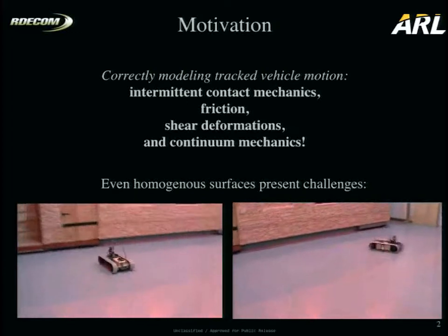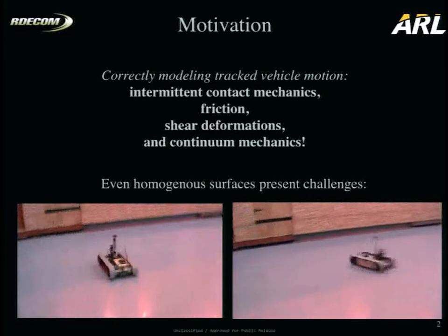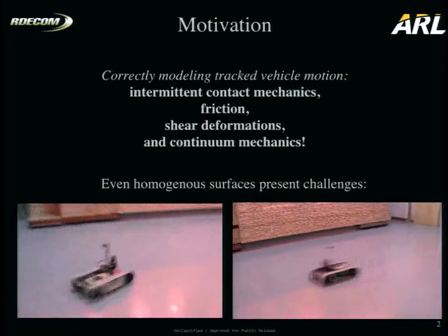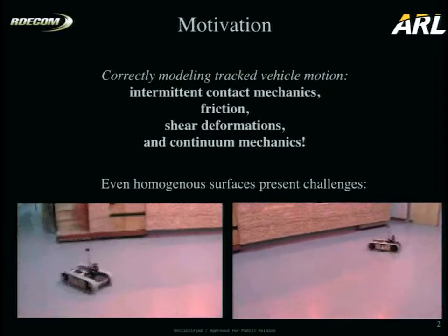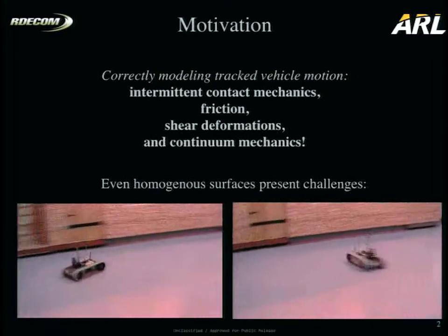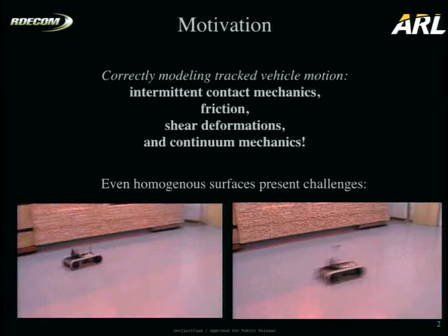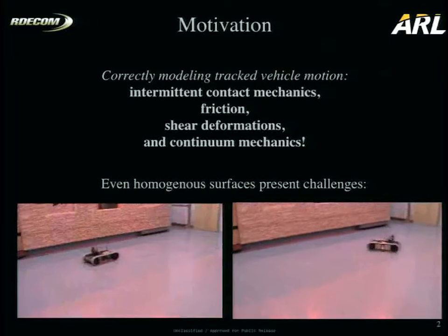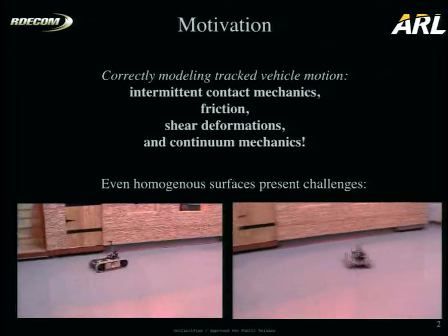One approach would be to rely on feedback in the system, but there's two main issues that we run into. First, there's no obvious error signal we can use at the rate and scale of a single rapid maneuver. If we were to look at GPS, it would be too coarse. If we were to look at vision-based odometry systems, you're dependent upon favorable feature-rich environments, and inertial navigation systems are going to be too bulky and expensive for the types of systems that we're interested in. Secondly, feedback requires you to have an understanding of the relationship between your dynamics and your control signal, and that relationship can be linearized. The systems we're interested in are subject to motor saturations, time delays, on top of the nonlinear effects that you have for the terrain interaction.